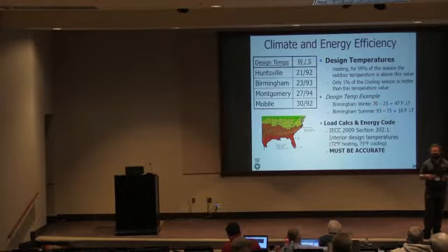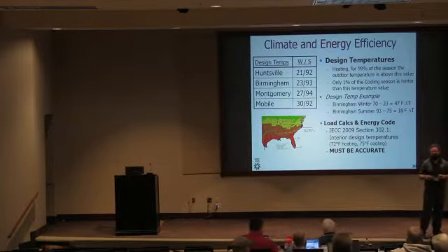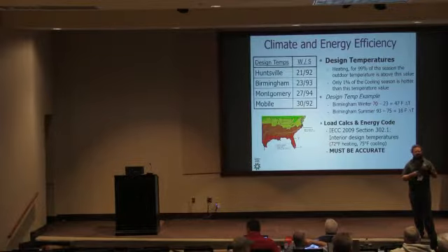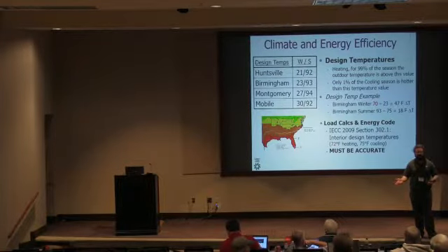If it's slab on grade and you have a radon issue, it's a lot more challenging. It can be done as a retrofit. You're just probably looking at a couple thousand dollars versus a couple hundred. But again, if you spray foam that roof line and you add a mechanical outside air ventilation system and you size it right to put the home under slightly positive pressure, you should mitigate the potential for radon risks. But again, building is a system. Is your guy who foams the roof line thinking anything about the HVAC system? Only if someone's talked to the homeowner before to make them well informed.